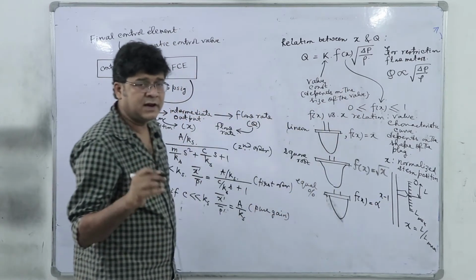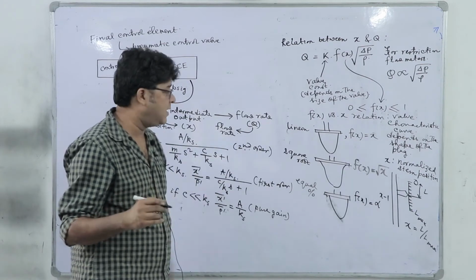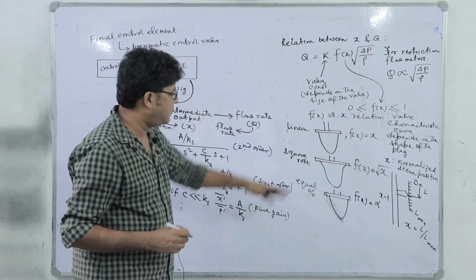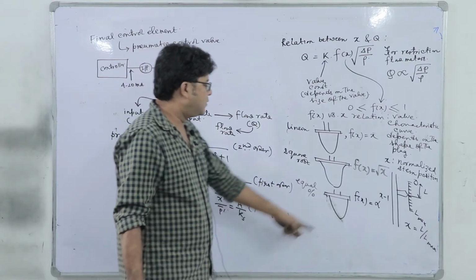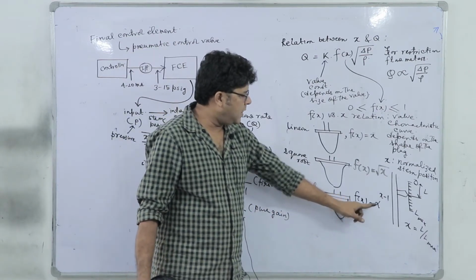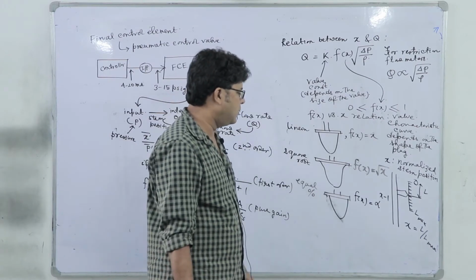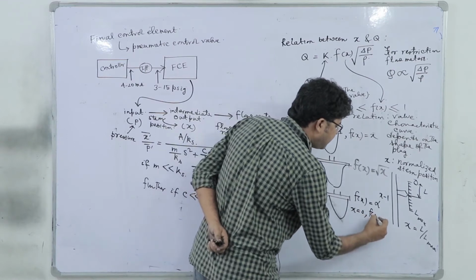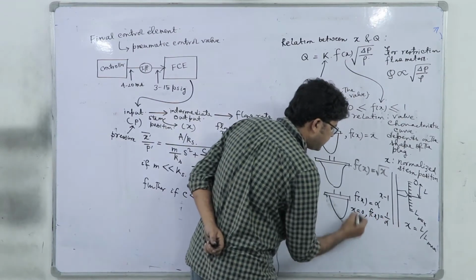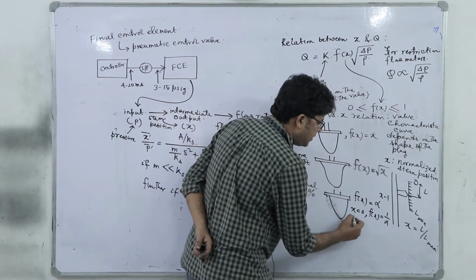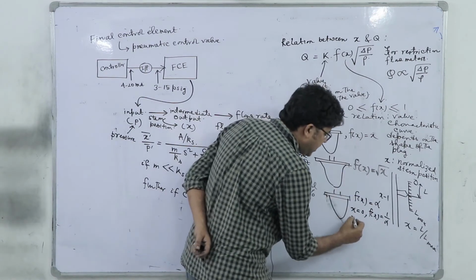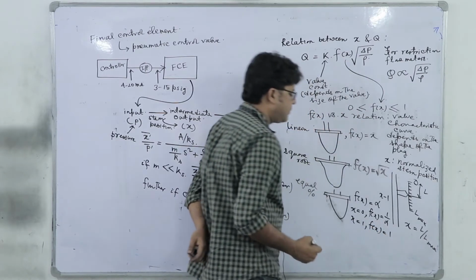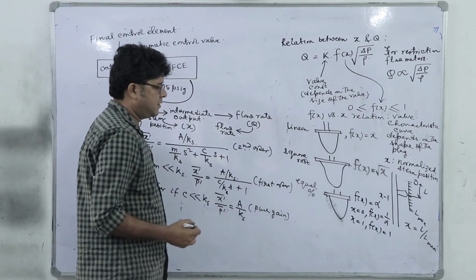There are alternative relations. We will discuss this equal percentage valve later, with detailed understanding of why it is referred to as equal percentage. Anyway, when x is equal to 0, f(x) is equal to 1 by alpha, so it is not a 0 value. It never attains the 0 value, and when x is equal to 1, f(x) is 1. So that is the equal percentage.